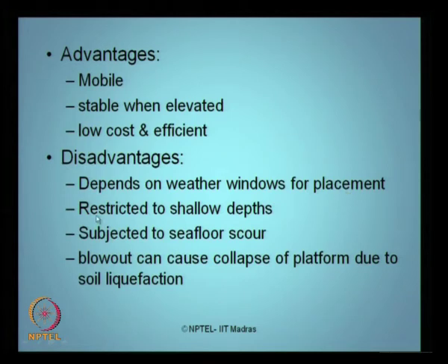They are strictly restricted to shallow water depths only, they cannot operate in deeper waters. They are subjected to very high sea floor scouring problems. A blowout, if it happens during the exploratory drilling, can cause a complete collapse of the platform due to soil liquefaction.